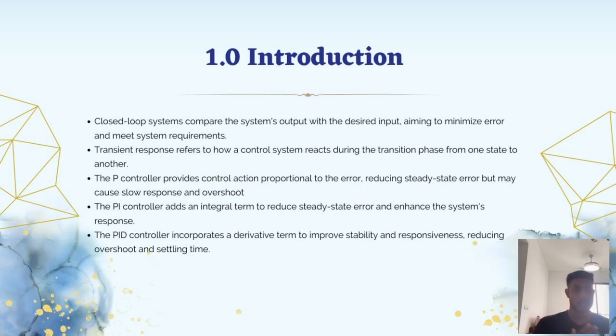Moreover, engineers can iteratively adjust the proportional, integral and derivative gains using the PID tuner and observe the system's response in real time. Utilizing the PID tuner in Simulink allows engineers to effectively tune P, PI, and PID controllers by ensuring the transient response requirements are met.